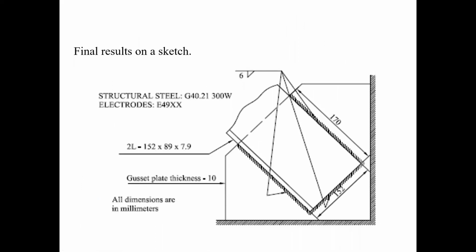And of course, you got to show everything on a sketch. So basically what you're showing here, guys, remember the welding symbols, okay? When the welding symbol is below, it's referring to the side that you're pointing at. So in other words, it's referring to this side, this side, this side, okay? That's number one. Now, the reason why you don't put weld all around, because if you put weld all around, they would also have to weld here. This means welding all around. And you're not welding all around, okay? Because when you put the second angle, I don't know how you're going to be able to weld it all around. There won't be room in there.